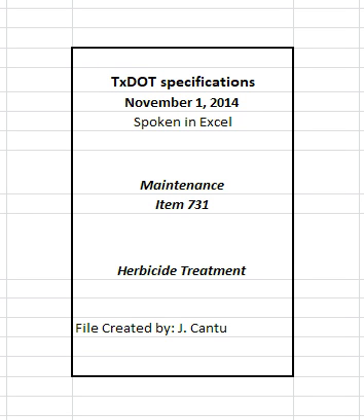6.8 Personal protection equipment. Follow the manufacturer's label requirements for personal protection of employees. 7. Work methods. Apply approved herbicide in accordance with the manufacturer's label recommendations, as shown on the plans or as approved. Add surfactant and blue dye marker at the manufacturer's recommended rate unless otherwise approved. Prepare herbicide solution to the rates shown on the plans using procedures on the herbicide container label.